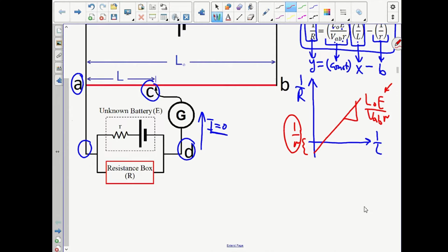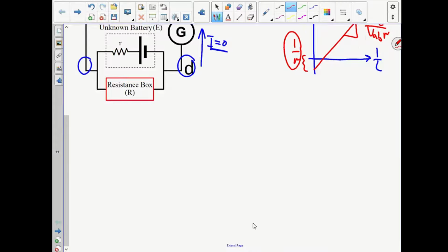The reason why we should use a voltmeter with high impedance is that you don't want any current to pass through the voltmeter. So for example, let's take a look at this simple circuit. And let's say that this is a resistance that has current I in it. And assume that you use a low impedance voltmeter to measure its voltage difference. So this is a part of a circuit. High impedance means high internal resistance of this device. So if this device has low impedance, this means that a large portion of the current will pass through it.